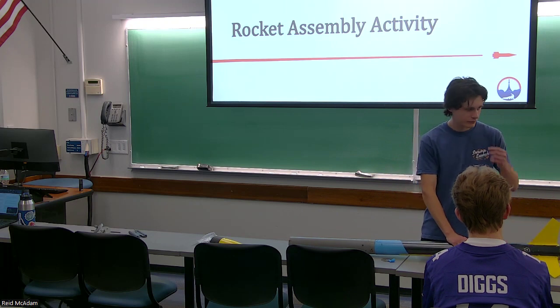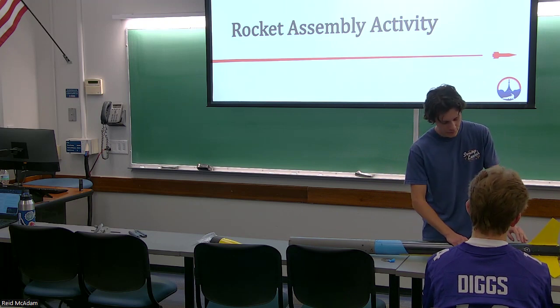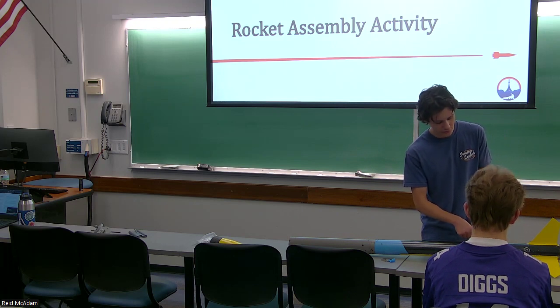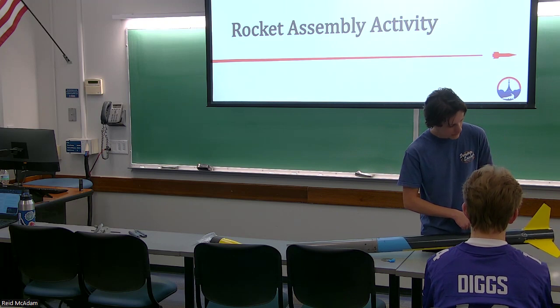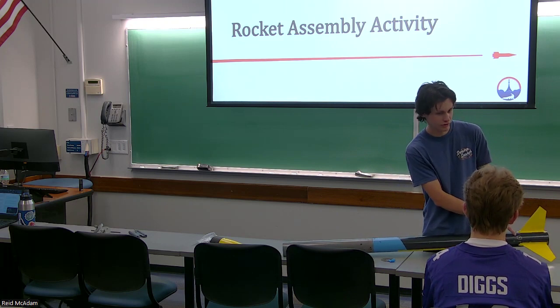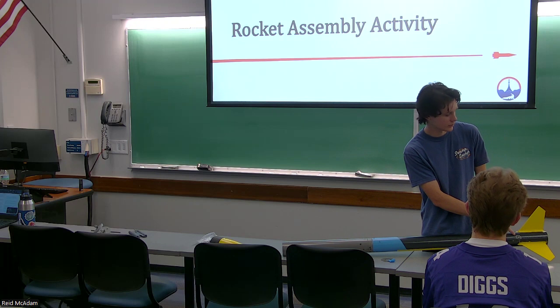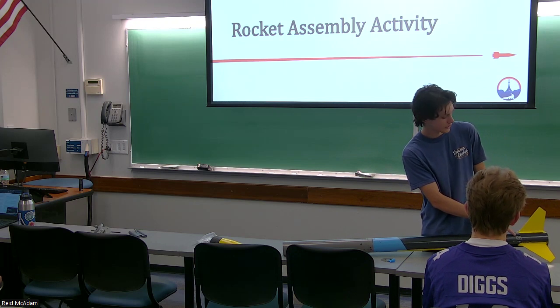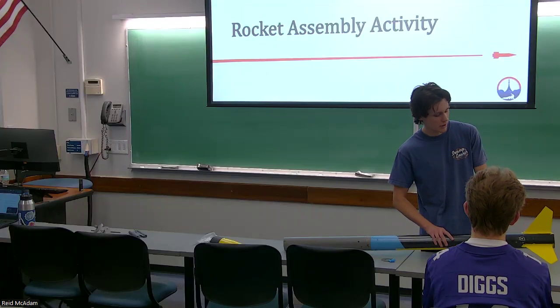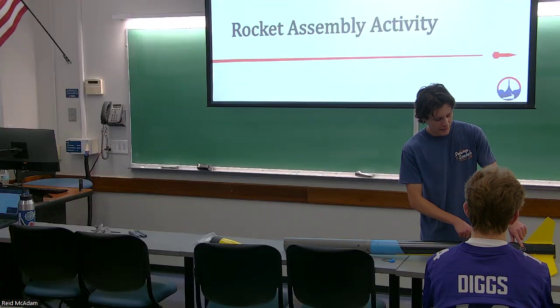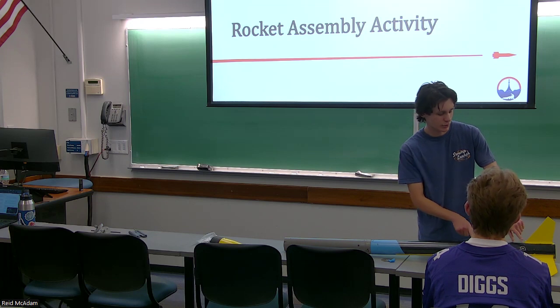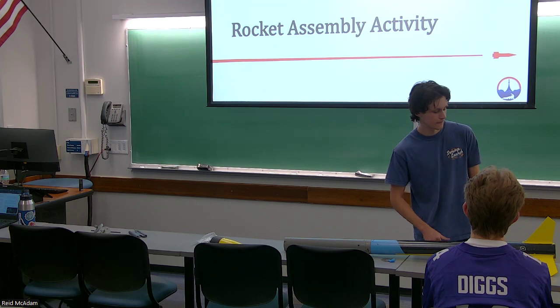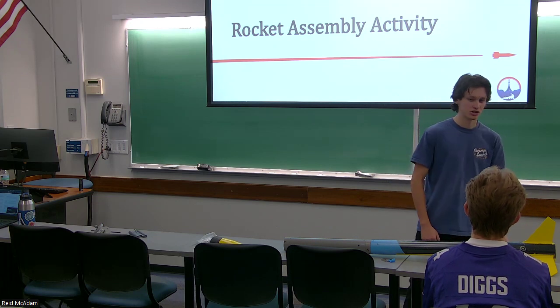On launch day, you're always going to do this. You're going to hang your rocket by a rope, and you're going to mark its center of gravity, which is this little symbol. Your center of pressure you just get from OpenRocket or whatever other simulation software you use, because there's no way you can really measure that like the weight. Then you go into your software and put these in, and double check that your weight's all good and that your rocket is still projected to be stable.